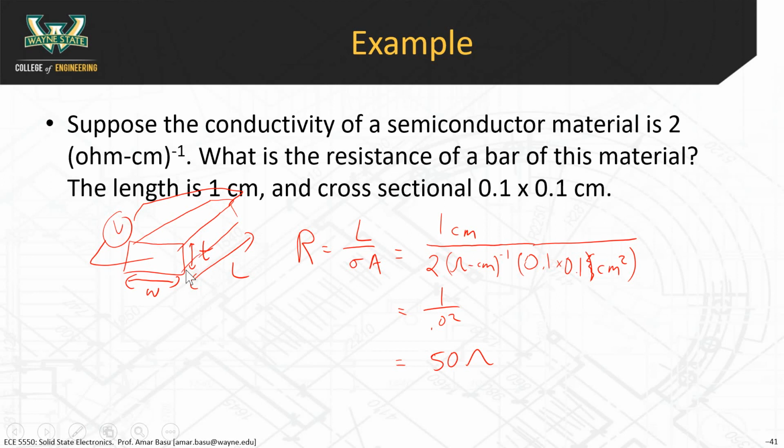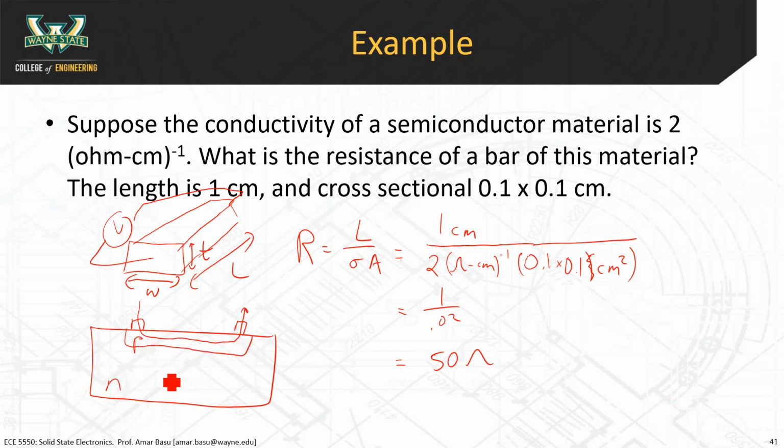When you do a diffusion process, typically what a semiconductor resistor would look like, let's say you have an N-type material, you create a diffusion zone here, and then you have your 2 contacts up here. So the current goes through the P-type material, for example, and it goes out this way. It doesn't leak out into the N-type material because there's a P-N junction there. That's beyond the scope of this discussion.